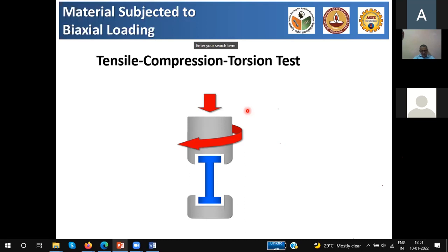I mean, because isotropic material will mean that you have the same properties in all directions, not only elastic properties, but also failure properties. And therefore, you really don't need to do tests in different directions. This is very important to note, because all our models that we are going to develop during this entire course will be multi-dimensional in nature. They will all talk of tensors, they will all talk of